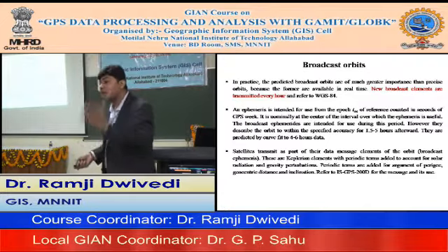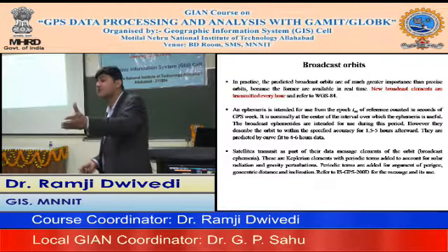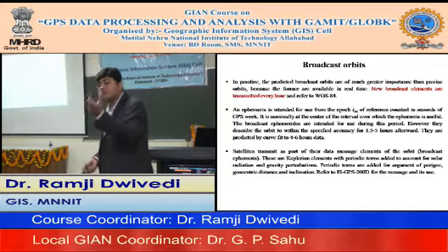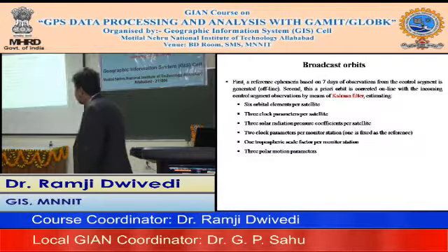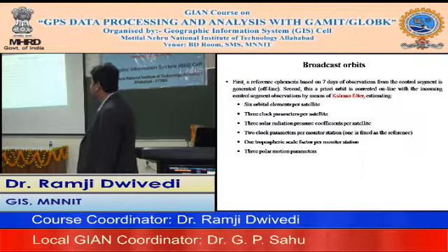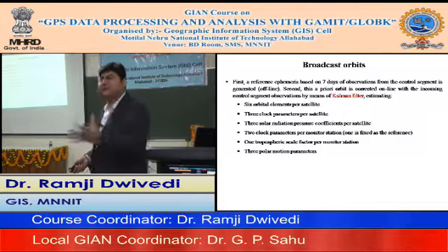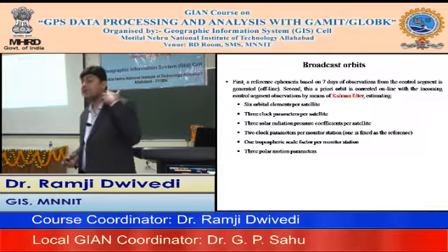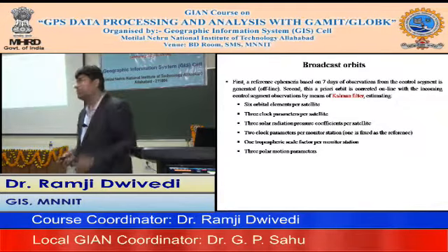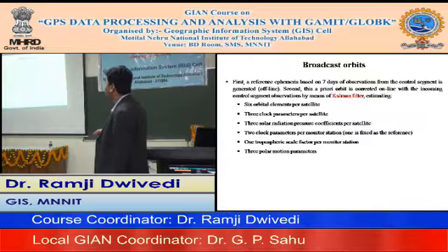You have to consider all parameters, all Keplerian parameters, as well as the forces, the constants which are given for the consideration of those forces. And then it is 6 elements per satellite, 3 clock parameters per satellite, 3 solar pressure coefficients per satellite, 2 clock parameters. So you see that every possible parameter which could be helpful for realization of its health status and its position in space will be transmitted, modulated onto the carrier to you.